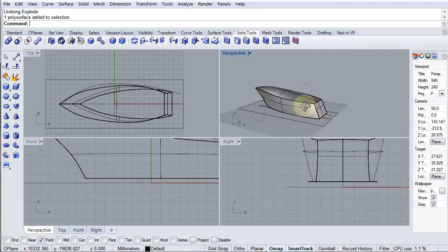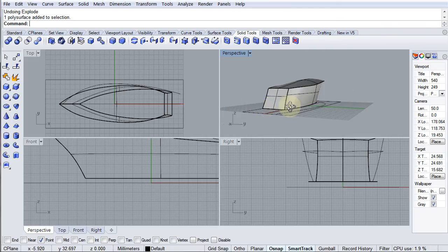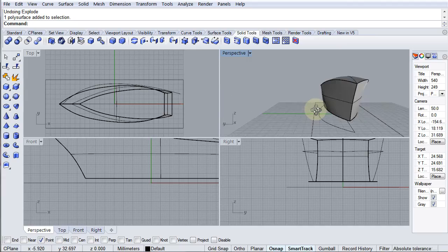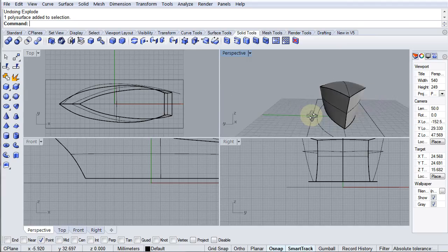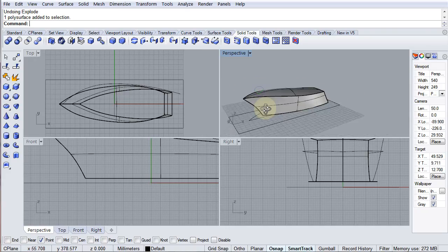And it gives you fairly quick automatic trims. I mean, you can do the same thing. It's a macro basically. You can do the same thing by trimming each edge one by one, selecting all the surfaces and then trimming one off the other one, using them all as cutting surfaces. But for this, it's much quicker. It does it all for you. It does the macro for you, and it leaves you with a fairly simple object behind, and gets rid of all the junk for you too.